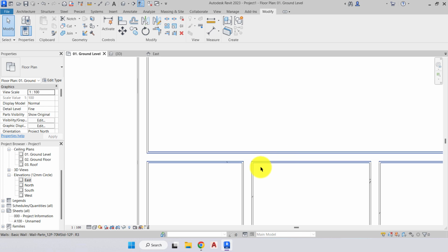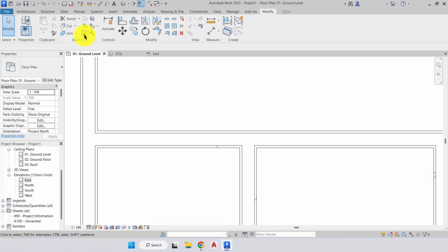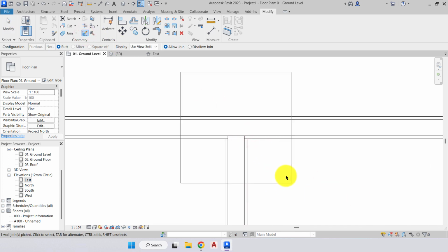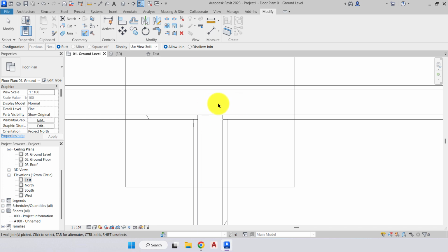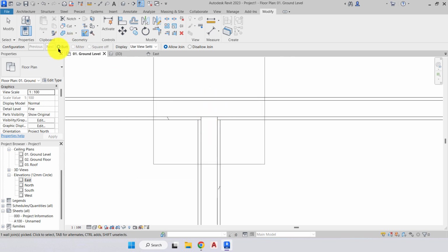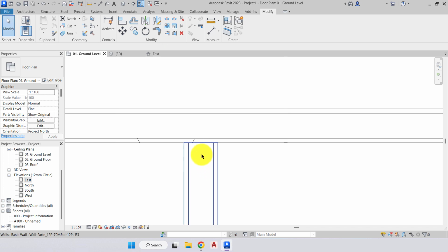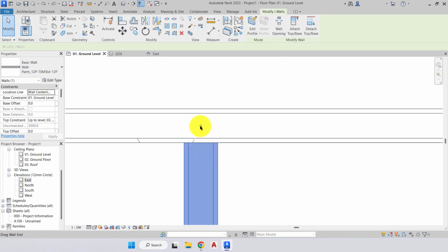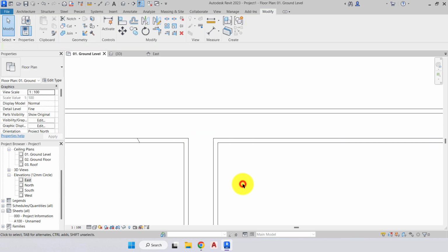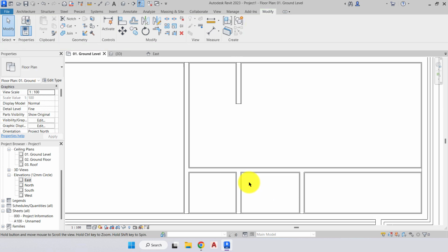Other areas we can use that tool would be with the internal partitions. So there the metal stud won't connect to the other metal stud. We can also use a don't clean that join. So the metal stud goes to the plasterboard, not to the metal stud. And to undo this, we just click, drag the grip out and then drop it back in, and it will create the clean join again.